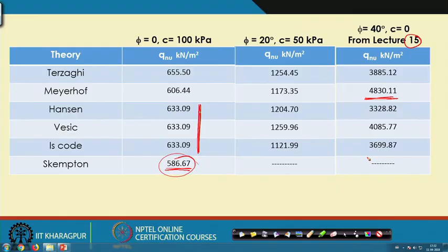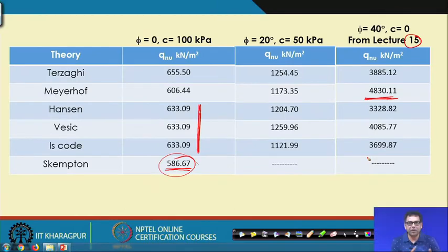So, now as I mentioned for cohesive soil, Hansen's theories give better prediction compared to Terzaghi's theory, but here I have used Skempton for all the problems on clay, because it is giving the lowest value. So, to be on the safer side I am using that, but here now the question is which equation we will use. As you can see, Terzaghi's expression is a simple one, and you can use it because it gives the average value, and it also gives almost similar values to other theories. It falls within the middle of the range that I have received.